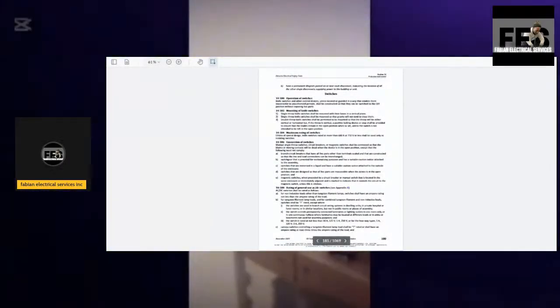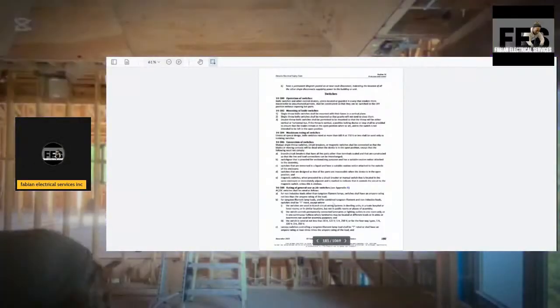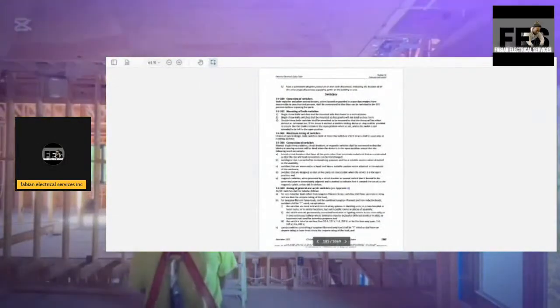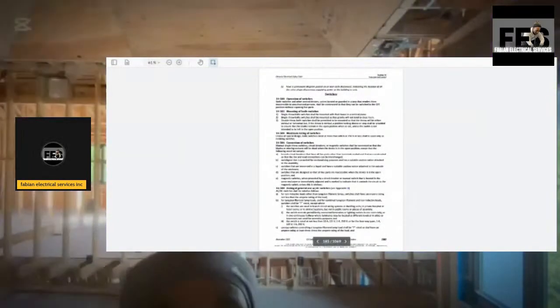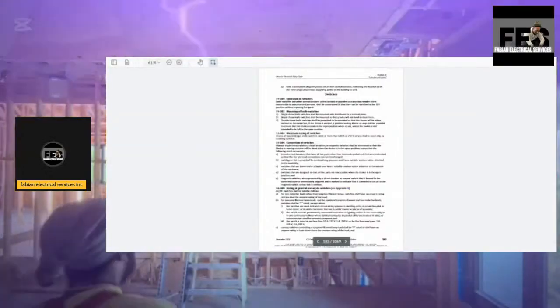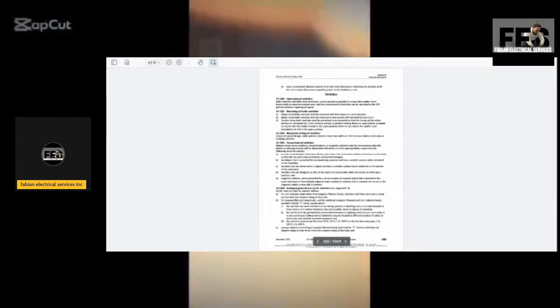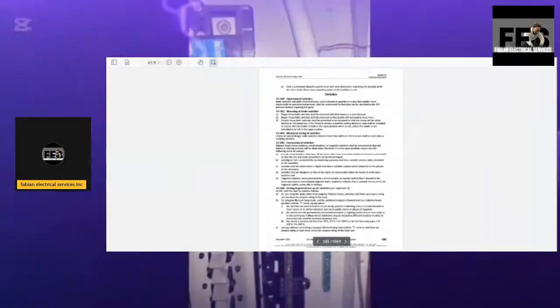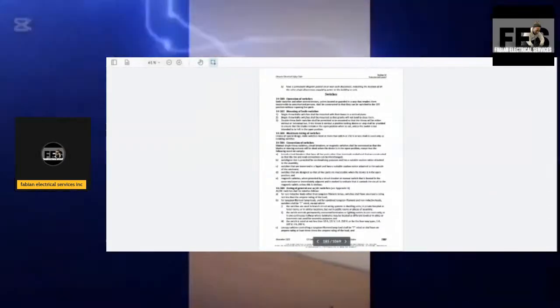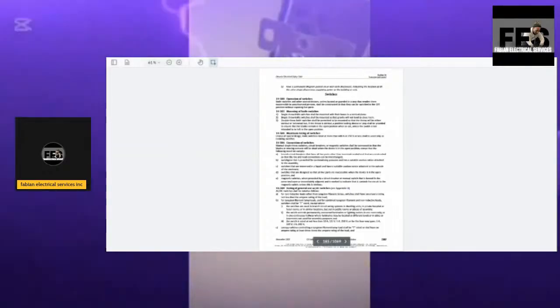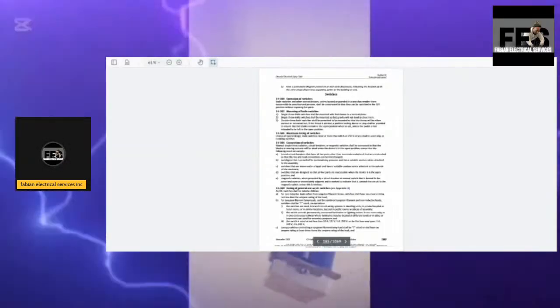For tungsten filament lamp loads and for combined tungsten filament and non-inductive loads, switches shall be T-rated except where the switches are used in the branch circuit wiring system in dwelling units, in private hospitals or hotel rooms, or in similar locations, but not in public rooms or places of assembly.